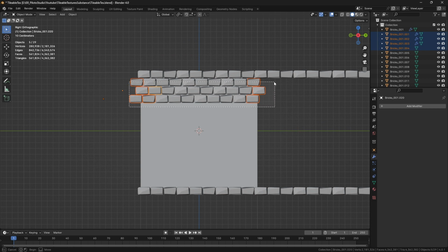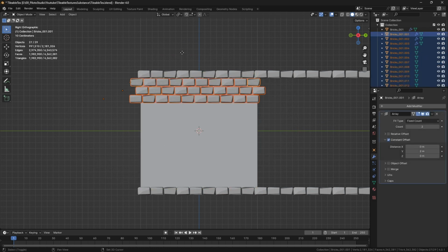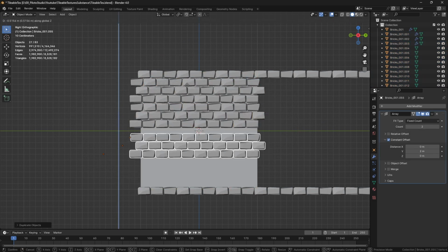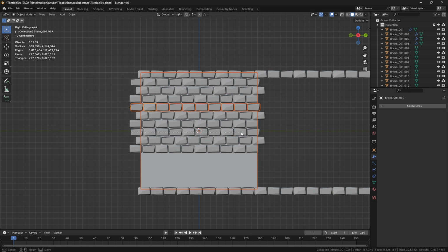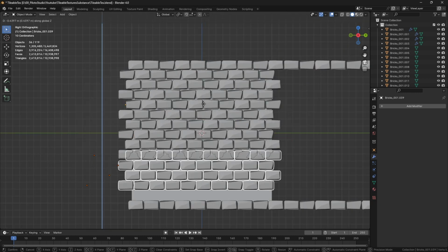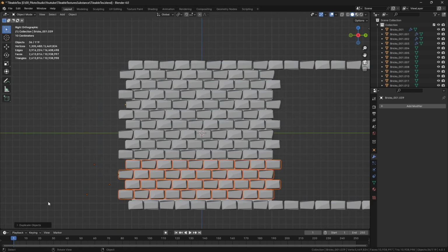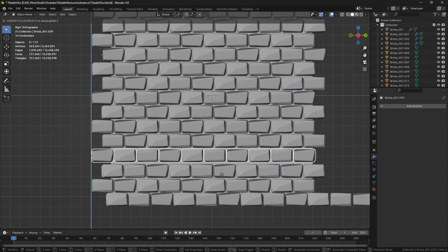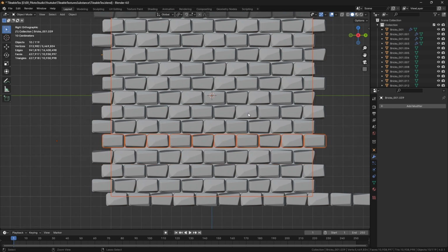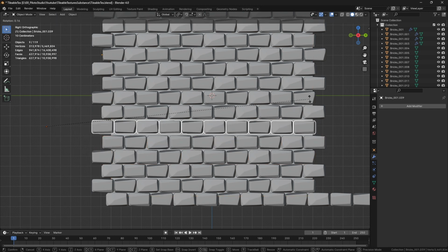Great. Now what I can do is I can duplicate this on the Z-axis until I hit the bottom. There's this, yeah, I forgot that. But that's okay. I guess we can just offset this where we're having this problem. And I'm gonna duplicate this last part again. And then great, that's all I needed. So I'm just gonna make sure I can scale parts. That's not gonna be noticeable. I'm gonna rotate a little.